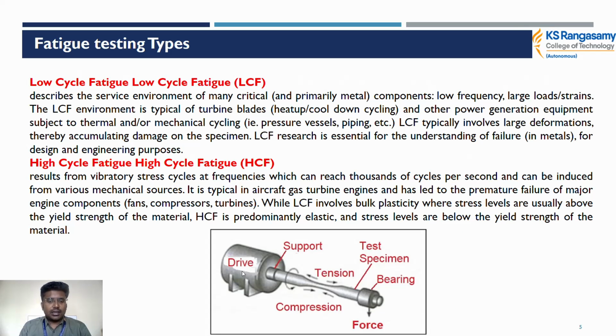Next, there are two types of fatigue testing. One is low cycle fatigue, LCF, and another is high cycle fatigue, HCF. Low cycle fatigue describes the service environment of many critical, primarily metal components at low frequency and large load. LCF typically involves large deformation, thereby accumulating damage on the specimen.